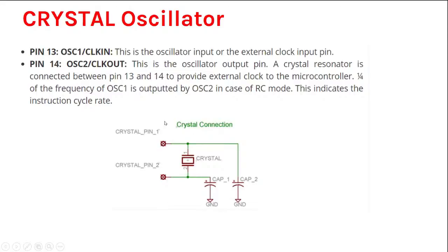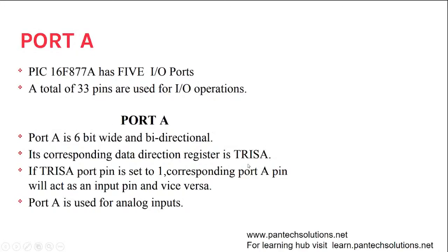This is the reference schematic which you have to connect, and you have the capacitors. Usually these capacitors will be 22 picofarad, 18 picofarad or 10 picofarad. And the next is port A.